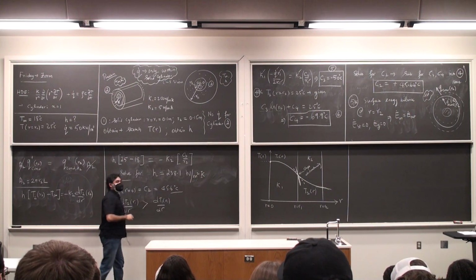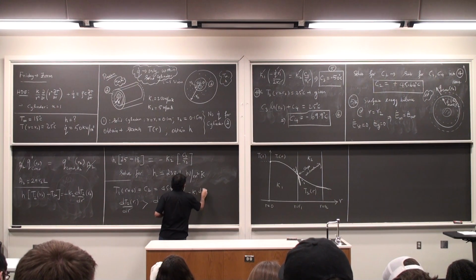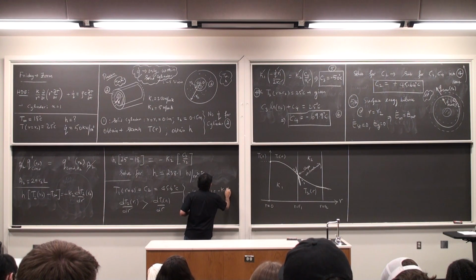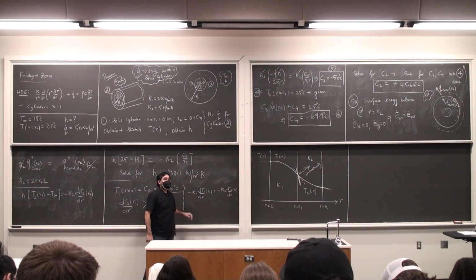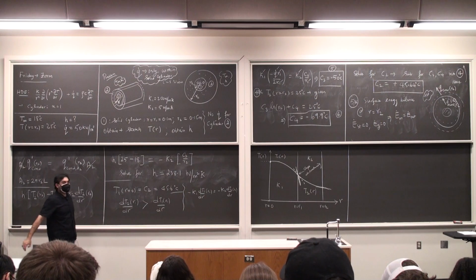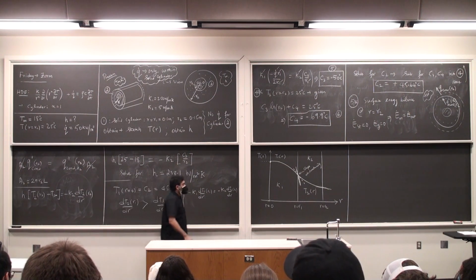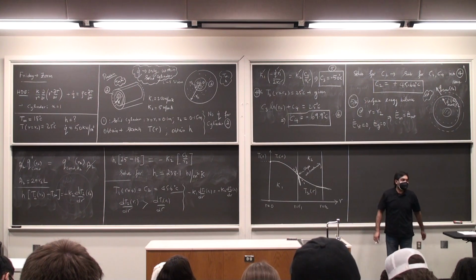I think I erased it, but here is the idea. Minus K1 dT1 by dr is minus K2 dT2 by dr, the negative sign vanishes. Okay. So I'm looking only at the magnitude of this one. Alright, any other questions on this problem, please?